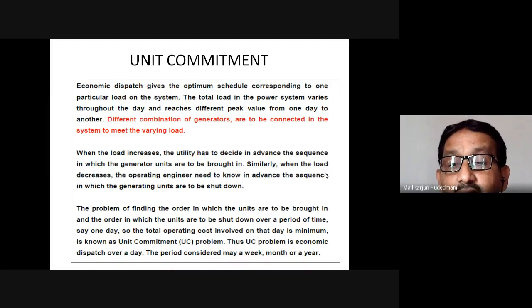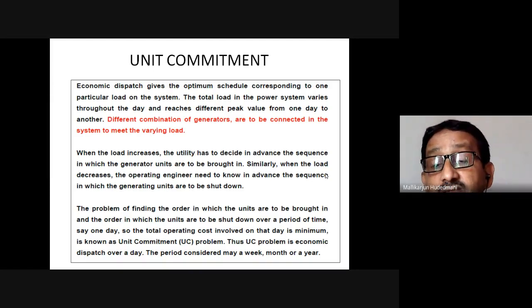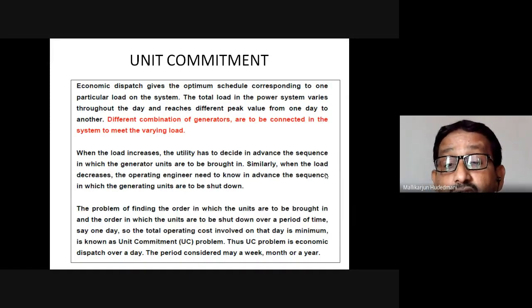Certain megawatt 0 to 100, another generator 0 to 200 megawatt. Like that, the connected generators together have a fullest capacity, the sum of their capacity, a certain working capacity that they have been set at and are generating, add them, and a minimum capacity, what minimum they can generate, PG min. So this schedule makes it possible. This is because on a given power station, the load curve is not a static load. It is from the minimum, a rising pattern, falling, again rising, again low, a peak, valley kind of pattern we'll find.